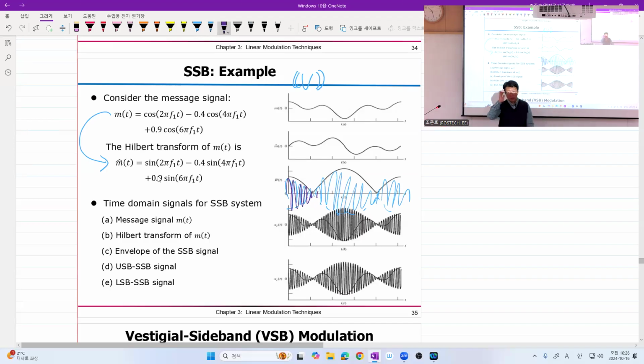If the bandpass signal has in-phase only or quadrature only, then those zero crossing points have exactly the same distance, but here it does not. But anyway, this is the positive and negative envelope of the Hilbert transformed signal, the SSB signal. Got it? And here, USB SSB looks like that, and LSB SSB looks like that. And you may say that, oh, what's the difference? What's the difference?